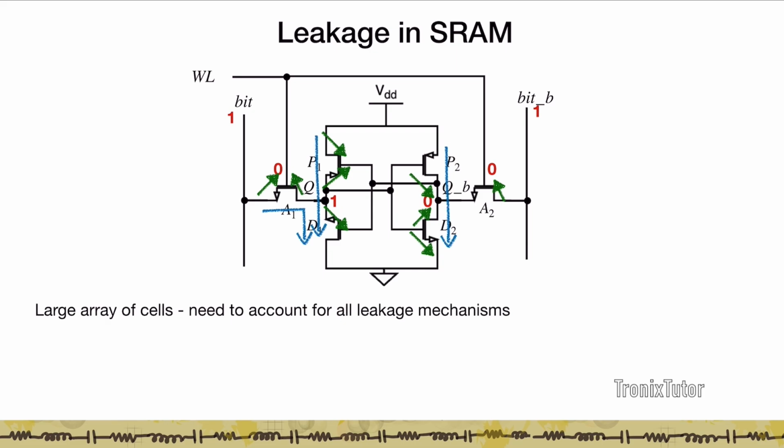So one of the primary goals of designing the bit cell is to ensure that the leakage in the SRAMs is as low as possible, and as the size of the SRAMs is going up and as you're scaling technology, SRAM leakage, as expected, continues to be a higher problem to manage. And so we then talk about using differential VDDs in the SRAM or shutting down the SRAM when not in use, etc. so as to arrest the leakage in this structure.